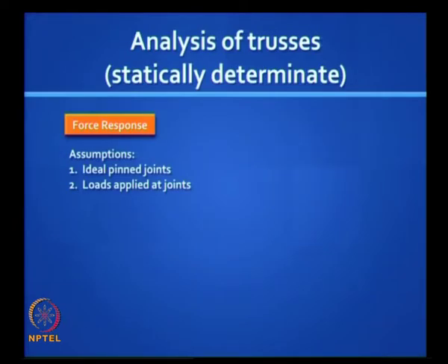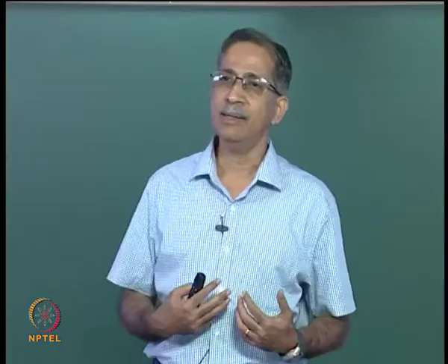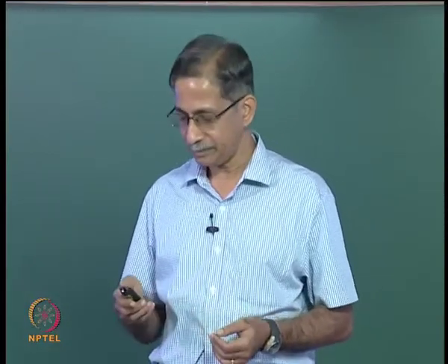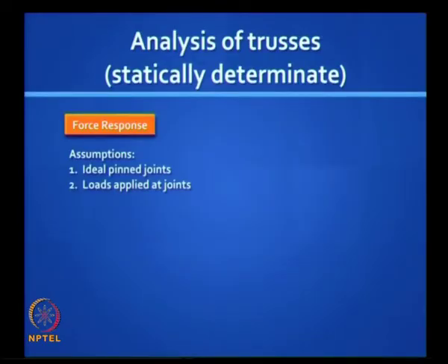So we are done with the topic of beams. We looked at how to draw shear force and bending moment diagrams. We also did some interesting cases where a bending moment diagram was given to you and you had to figure out what loading caused that bending moment. We also looked at how to calculate deflections and slopes using the direct equilibrium method. We now quickly move on to the topic of trusses.